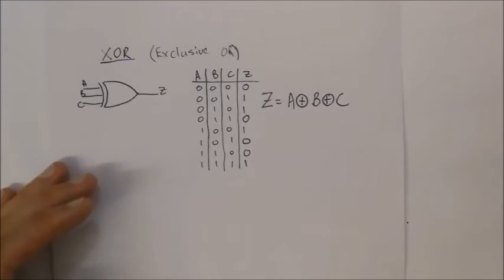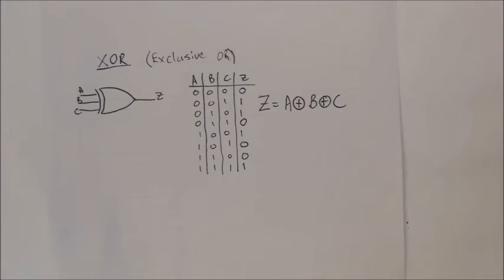Okay, so we've basically looked at the different gates that there are. Now, essentially, there are 3 different conditions or 3 things that you could be given, and you've got to find the other 2. So, for example, I could give you some logic diagram, and I could ask you to find the truth table or find the expression.